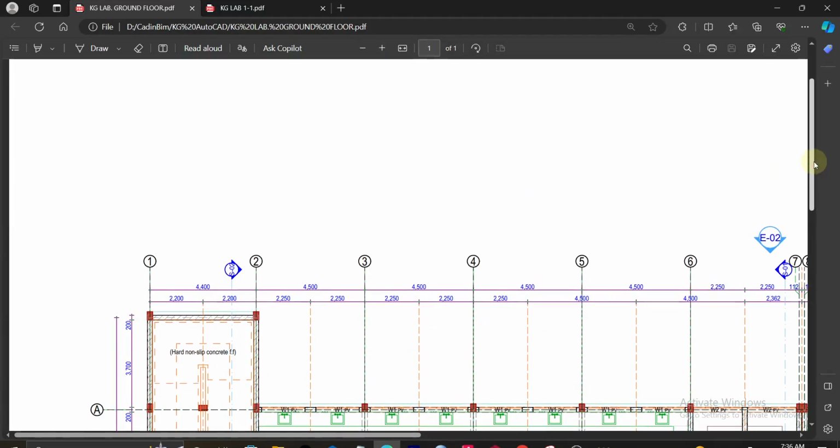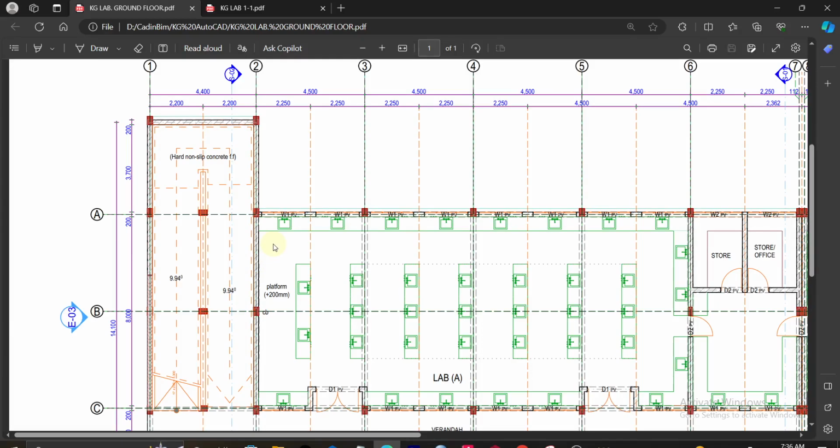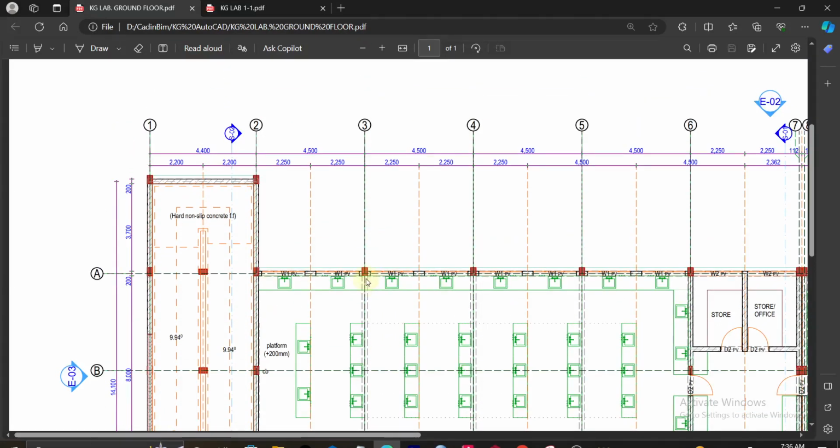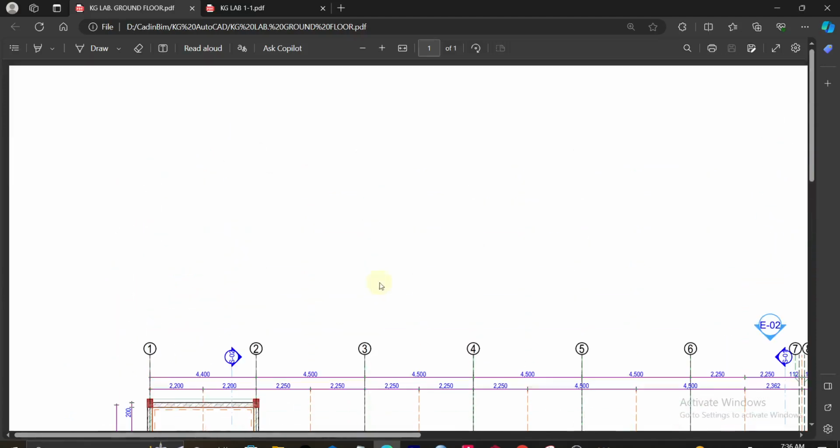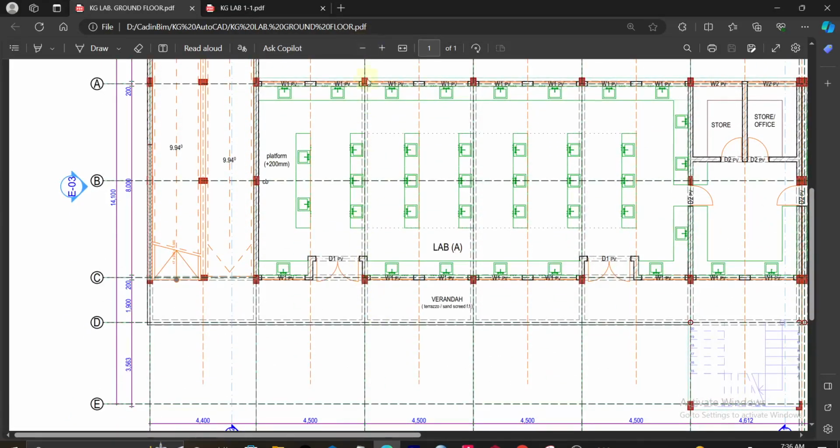Based on column orientation and the knowledge that I did previously, this 450, this 450, so this column and this moment here, they will cancel. So we'll be having a moment here of this column here, which is about 8 meters, but however, consider half of it, that's about 4. So the column orientation should be in such a way that the shorter span of the column is perpendicular to the longer side of this column here. So we'll be orienting our columns in this manner. Let me now go and orient my column properly so that we are together.